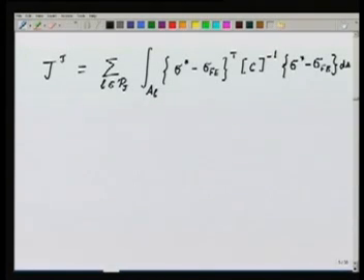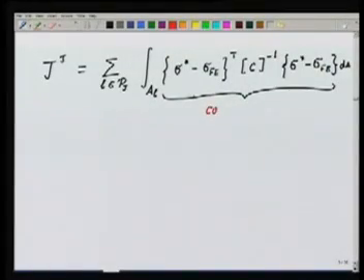See what we have done. This quantity is actually the complementary energy corresponding to the stress given by sigma star minus sigma Fe. So this is the complementary energy of what we would say is the error between the smoothing stress and the actual finite element stress. So we have defined this functional.